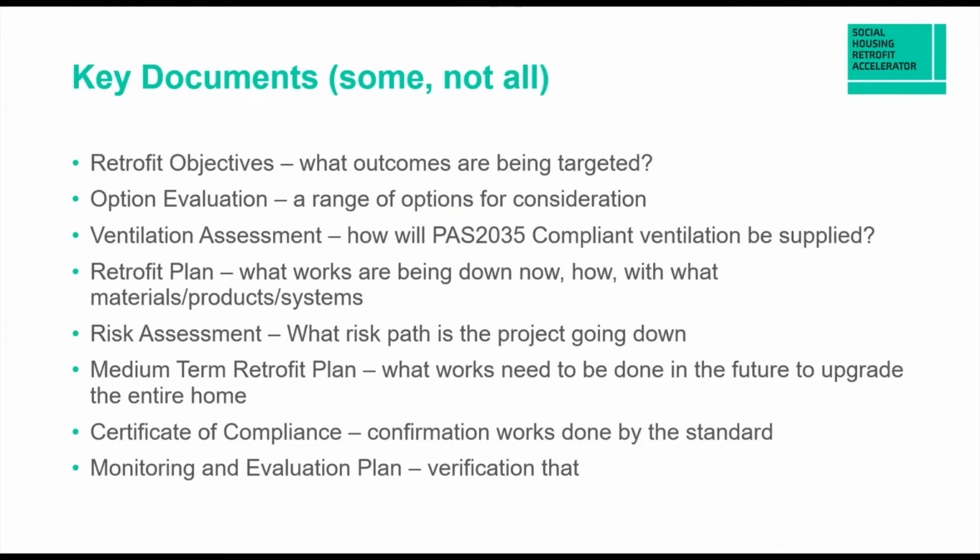So they're not the same. So the key documents for retrofit coordinators that we need to lodge are the retrofit objectives, the intended outcomes, what was to be targeted, the option evaluation, the ventilation assessment. So this is its own specific document to make sure that the ventilation has been addressed, it has been assessed, and it has been remediated if it was required.